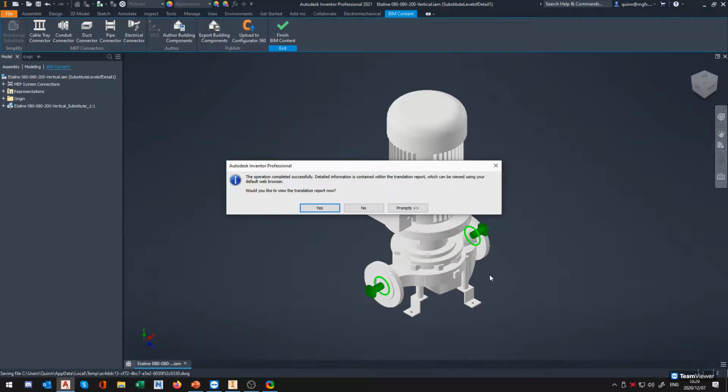And then when you're exporting out, just remember, because it's a different kind of file type, and unfortunately, due to the limitations of Plant at this stage, it doesn't have a direct connection back. So that ADSK file, once it's exported, is kind of broken apart. There's no linkage between it, meaning that whenever you update something, you will have to re-export it again. It's not a major problem, but just be aware of it and it won't catch you out.